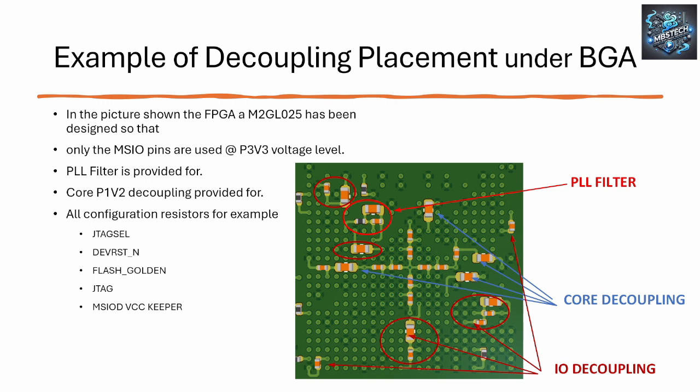As such, all those I/O won't have wires connected to them, so you'll have area to place extra decoupling. Maybe even, if you're clever enough, to put your 1.2 core volt power supply there, and actually get an extremely close coupling of your core voltage, VRM, and decoupling capacitors. So you need to play around with these things. Okay.